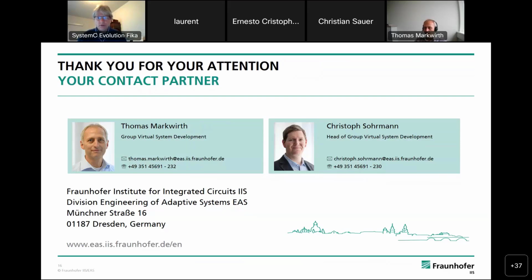Okay, we used here an algorithmic ECU model, so it is not cycle accurate in that case. But in principle it would be possible to integrate, at least for the software parts and the controller parts, a cycle-accurate approach by integrating the instruction set simulator. But nevertheless, the environment is not cycle accurate. You're right at that point. But this also reduces the performance really extremely.